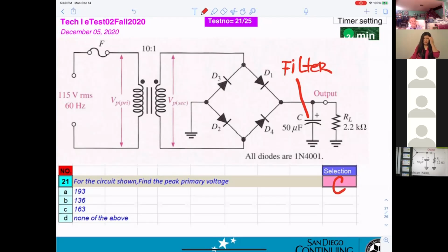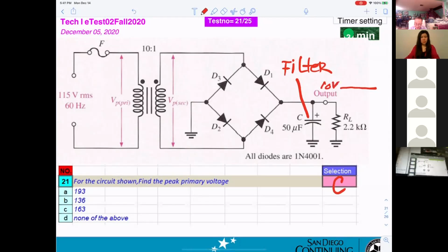Okay, and that's for reducing the ripple from the output? Exactly. The name of that capacitor is filter. Okay, you understand the output here, they want 10 volt, whatever voltage DC. Okay, 10 volt for example. However, on the top, they can get ripple. That means the noise. So that capacitor here, they call a filter.